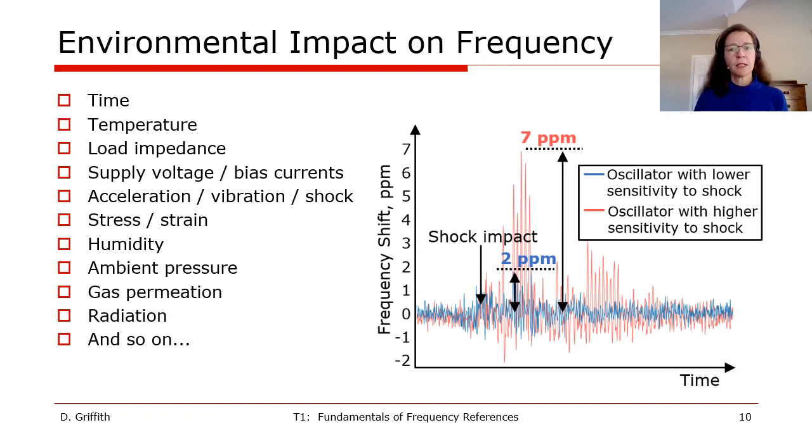So far, we have seen examples where the frequency changes versus time due to circuit aging and also due to temperature, as shown in that example tuning curve on the previous slide. However, the reference frequency can also be impacted by changes in the load, the supply voltage, or the bias currents. If it's operating in a harsh environment, such as a car or a factory, it could be impacted by acceleration,